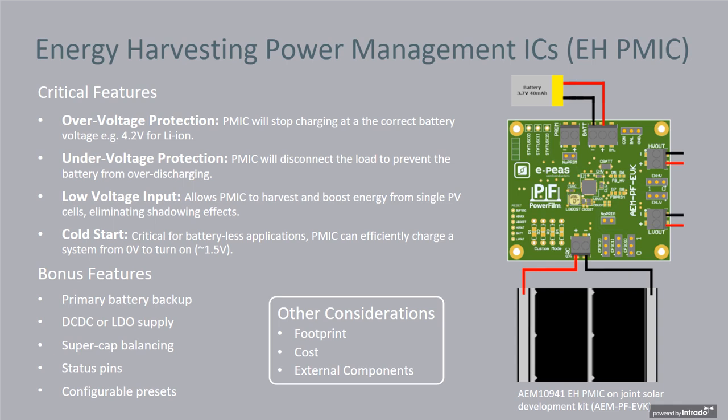And then those common sense considerations: footprint. Do you need the layout to fit in a super compact wearable? Are you working with a thermostat where maybe you've got a little bit more room to play? Cost, external components. So those are things that you should consider for the energy harvesting power management.